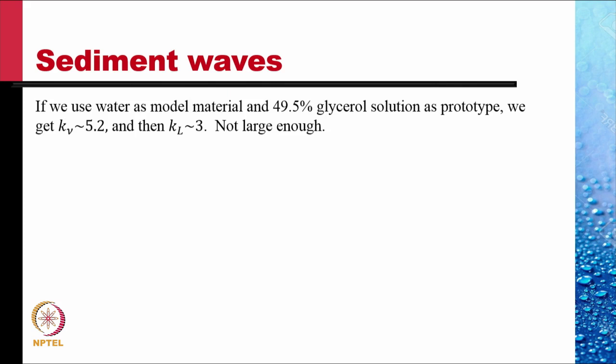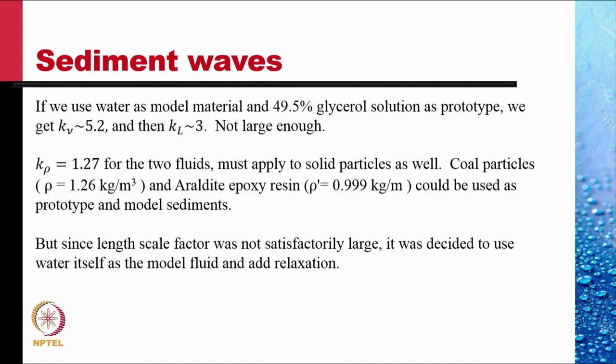If we use water as a model material and 49.5% glycerol solution as prototype, we get K nu equal to 5.2 and then KL is like 3, which is not large enough. And if we do that, K rho equal to 1.27 for the two fluids must apply to solid particles as well. The density ratio for the glycerol and water is 1.27, and so this must apply to the solid particle as well. The same density scale factor should be used.